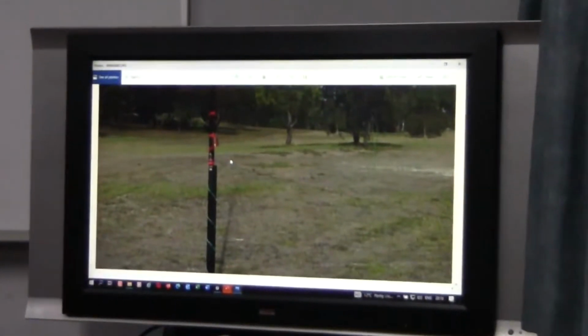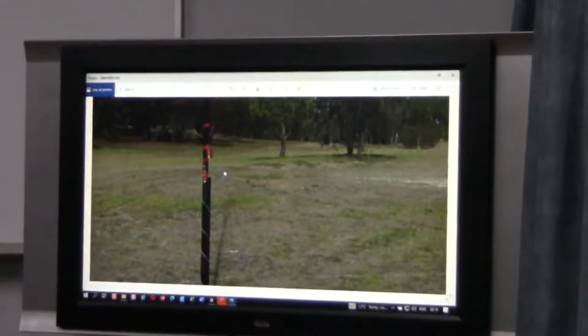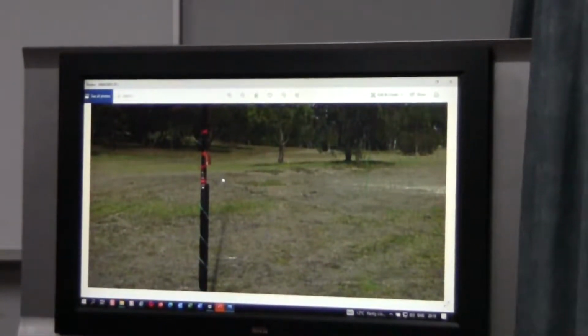And you can see the ground radials. They're suspended about 1.2 metres above ground using, maybe you can just see it over here, just garden stakes, 1.2 metre earth stakes, with an insulator at the end. Now these radials, if it was a true quarter wave ground plane with quarter wave radials, they'd be about 10.5 metres long. I was experimenting with shortened radials here, and I won't go into the operation of that, but they're only half the length. And there's a compensation scheme going on here, so I won't worry about it.